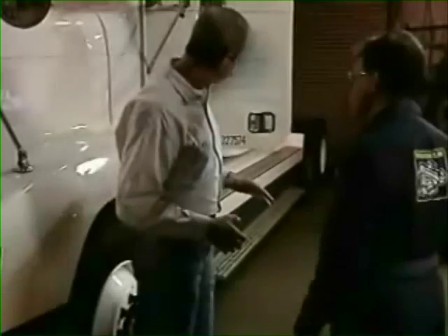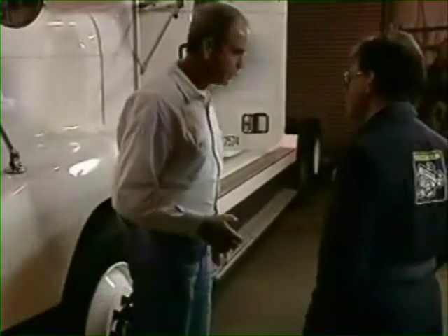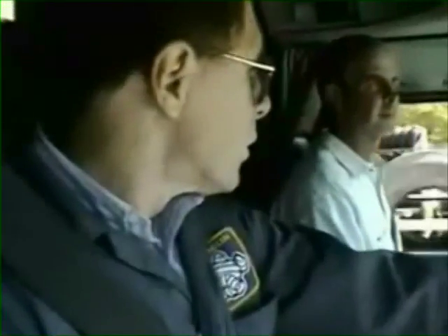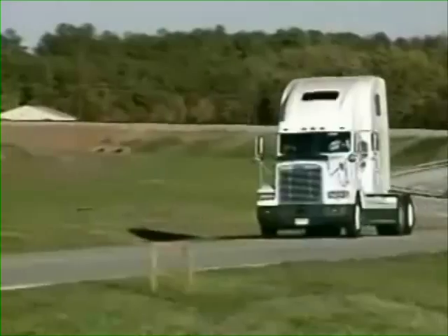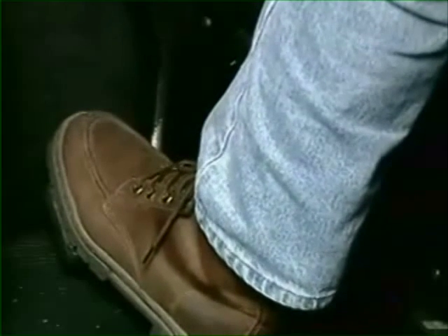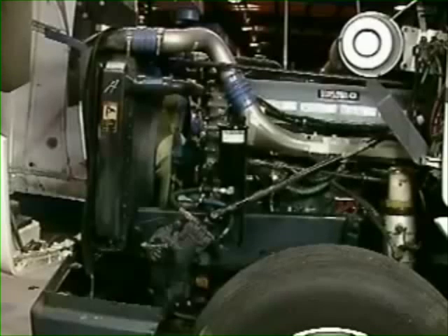If, after talking with the driver and inspecting the vehicle, you cannot determine the source of the vibration, then go for a test ride. Be sure to instruct the driver to simulate the exact conditions under which the sensations are being experienced. Warm up the tires for at least 5 miles. On a smooth road, disengage the clutch. If the vibration disappears, then it is engine-related.